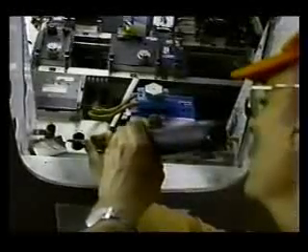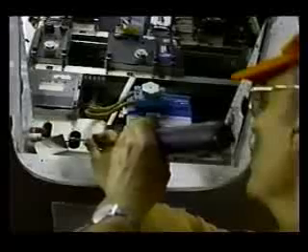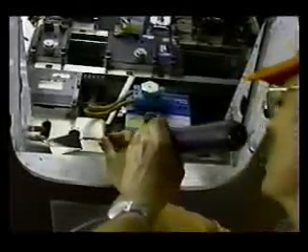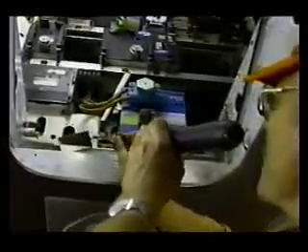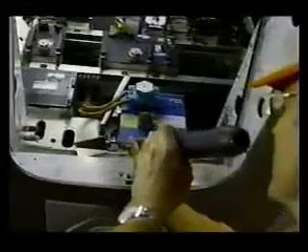For extensive corrosion damage, a service difficulty or M/D report should be forwarded to the local FAA Flight Standards District Office for later analysis. If you are finding abnormal amounts of corrosion on your aircraft, your previous inspection or preventive maintenance program obviously did not do the job. Since you are the one who is most in tune with your aircraft's physical condition and operating schedule, you are most qualified to revise your corrosion program.